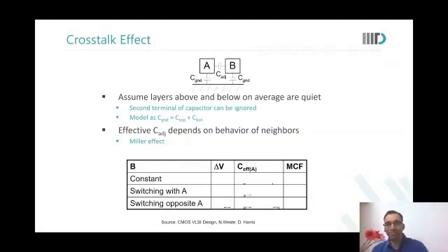Okay, sir. But in the last point you mentioned that if we are talking about a huge driver of current, then we will increase the number of contacts. So let us assume that 10 were what you got by default from the P cell. That is the maximum contacts you can put. We said that in a typical case, when it is not a very big driver, we will reduce from 10 to 5 or 10 to 4. But if this driver is operating every cycle, if the activity rate of this driver is very high, then electromigration rules may require me to put 7 contacts instead of 4 or 5. So that even after aging, things are fine.